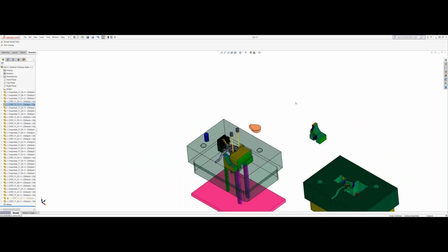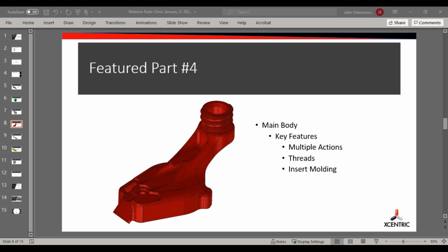With regard to the hand loads, did you build duplicate sets that the operator could have prepped and ready to load? Yeah, we do that. It just depends on the situation and the part. If we assume up front there's going to be a lot of wear, or very fine details that could easily get damaged or wear out, we would consider making duplicate pieces depending on the particular part.